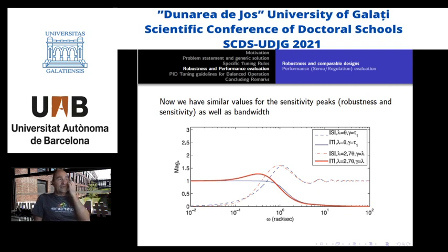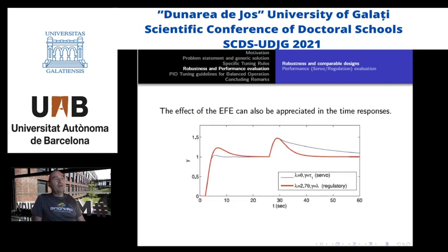As you can see here, okay, even in this case, the regulatory design, the complementary sensitivity transfer function for the red design has still some peak compared with the other one that is completely flat. Okay, so in this way the designs can be compared, and in the high frequency region you can see that both designs behave exactly the same way. Okay, and then if we compare them in the time domain, we find something like this.